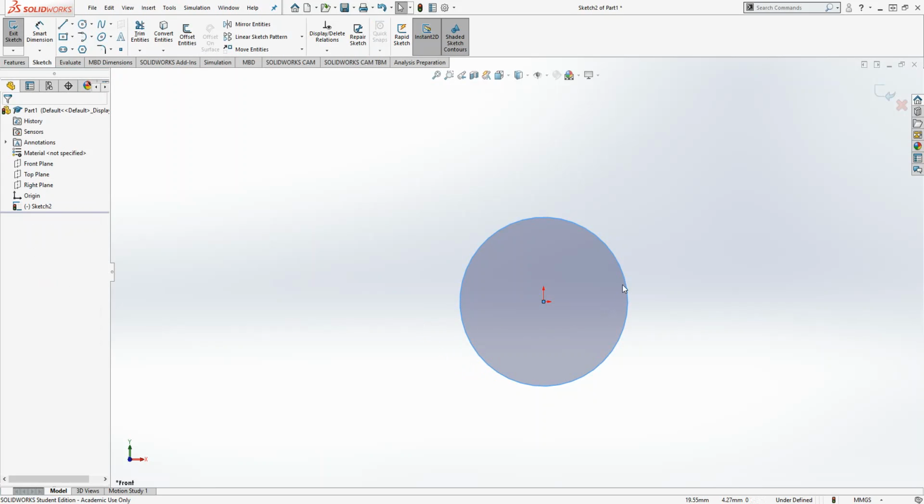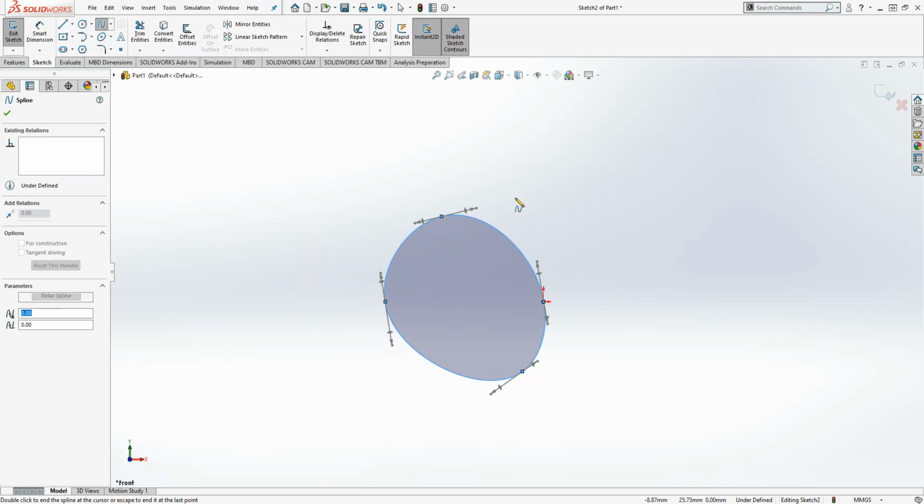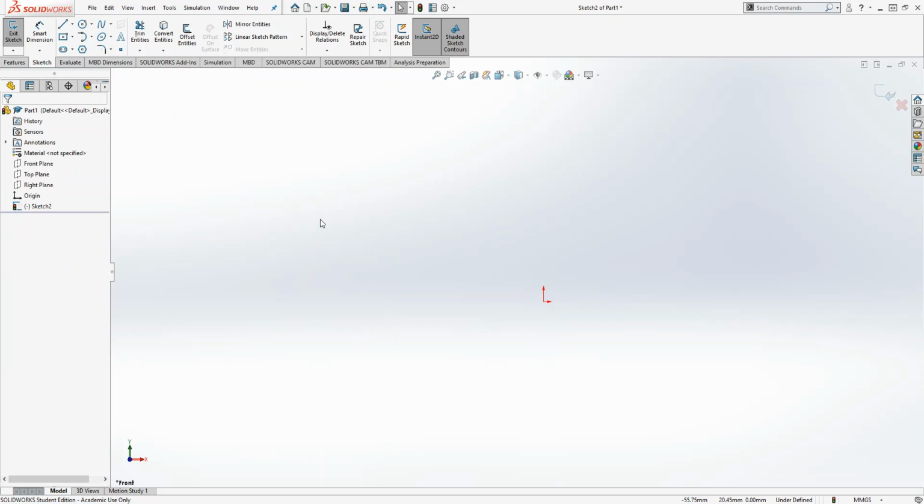Another thing we have is the circle tool, right? So I click the circle, and I can click. Now there's different options for circles, but I'll just pick the normal circle, right? I can click to define a center point. So I'll do a center point on the origin, and you can see it gives me kind of that radius in millimeters, because that was my previous measurement system. Maybe I want to make it a 2 centimeter radius circle, roughly, right? And I can click. And since it's 4 little curves, or 4 90-degree curves, right, you'll see that this is a full defined circle, and I could extrude this, right?